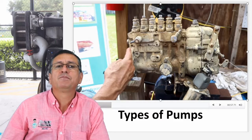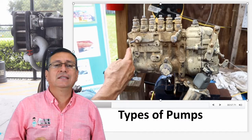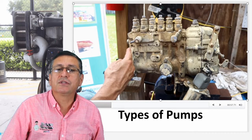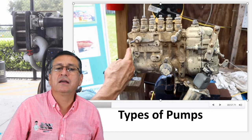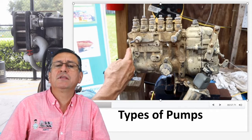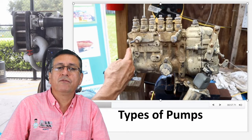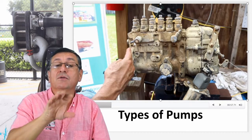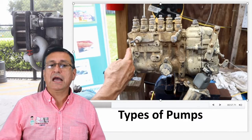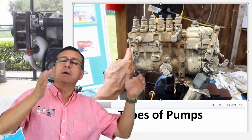This small block is like a replica of the big engine. This is a perfect replica of the big one. Internally, we are going to study right now, we have a camshaft here, and we have cylinders with pistons. The name of those elements, cylinder with piston, is the plunger. You have 1, 2, 3, 4, 5, 6 plungers in this particular small engine, because the big engine is 6 cylinders. And this small block works in parallel with the big block.